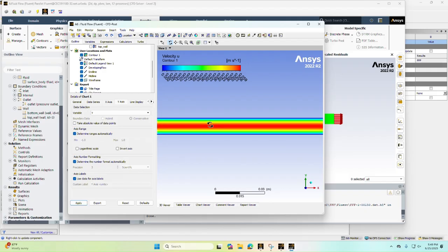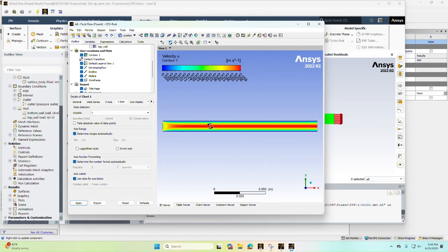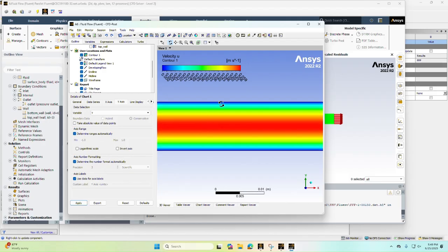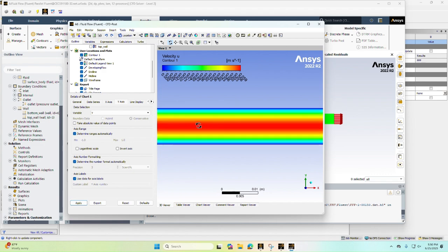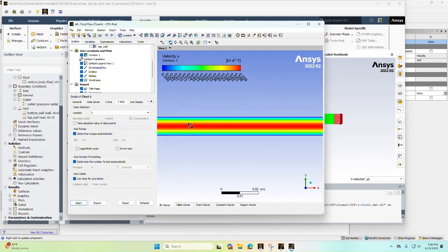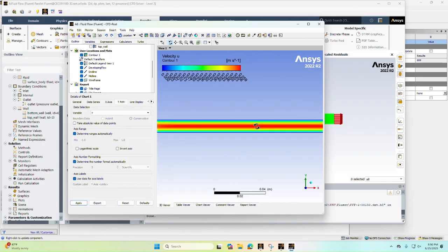This is due to the shear viscosity of the fluid, or I guess shear modulus of the fluid. Right, you got a stationary surface here and a constantly shearing material, where the least amount of resistance is in the middle, so it'll be the fastest.